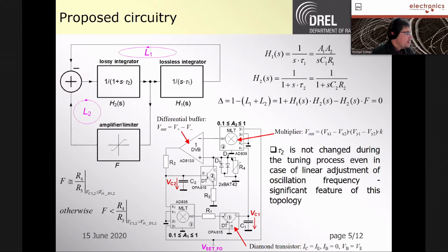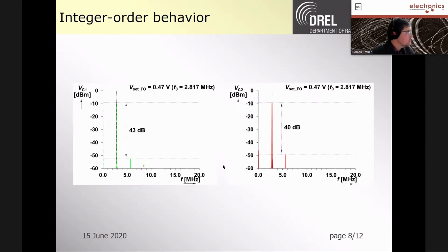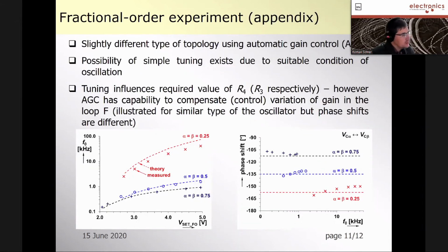And also, as we saw, regarding the inertiality of the feedback amplitude limitation, we used some standard diodes. It's not a very good idea, because we have to use better types of diodes, and it also limits the available ranges of amplitudes.